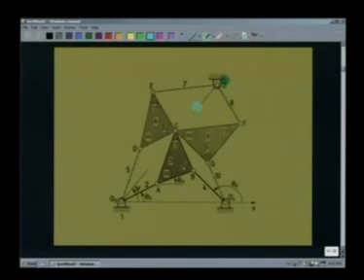As a result, now we have an assembly of links where there are three 4-bar linkages: one 4-bar linkage consisting of links 1, 2, 3 and 4 with the coupler point at C. There is a second 4-bar linkage consisting of links 1, 8, 9 and 10 with the same coupler point C, and the third 4-bar linkage consisting of link number 1, that is the fixed link, link 7, link 6 and link 5.